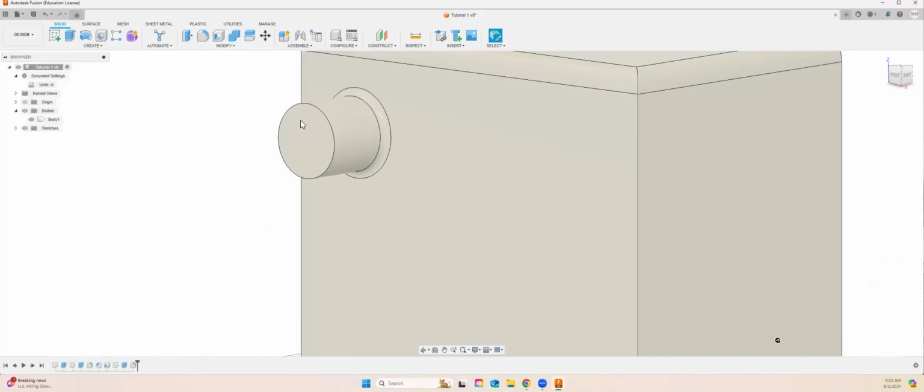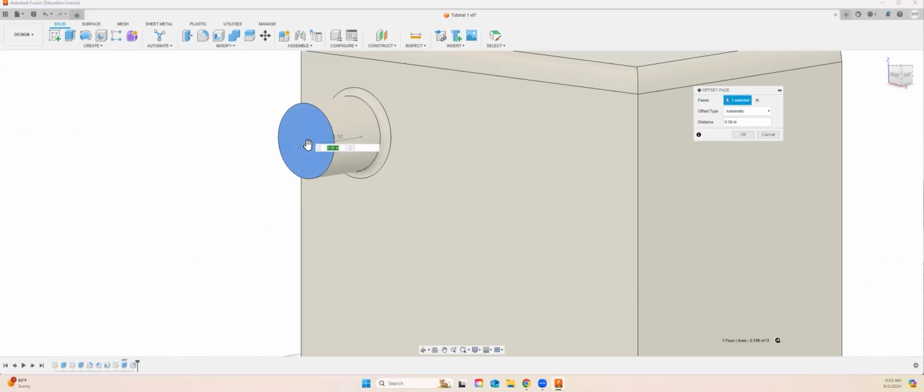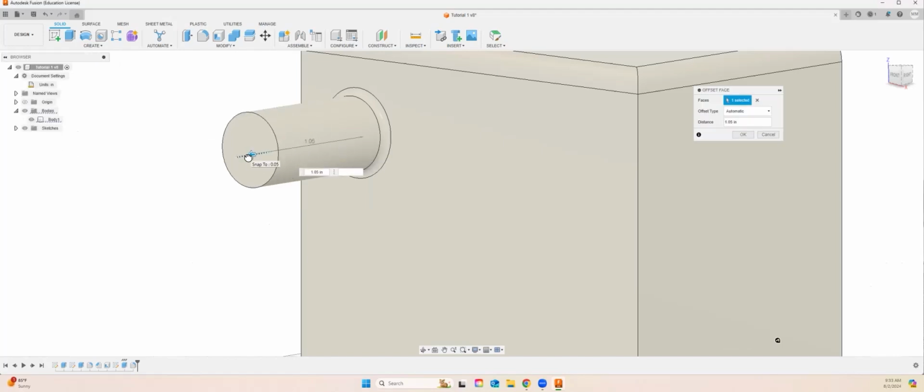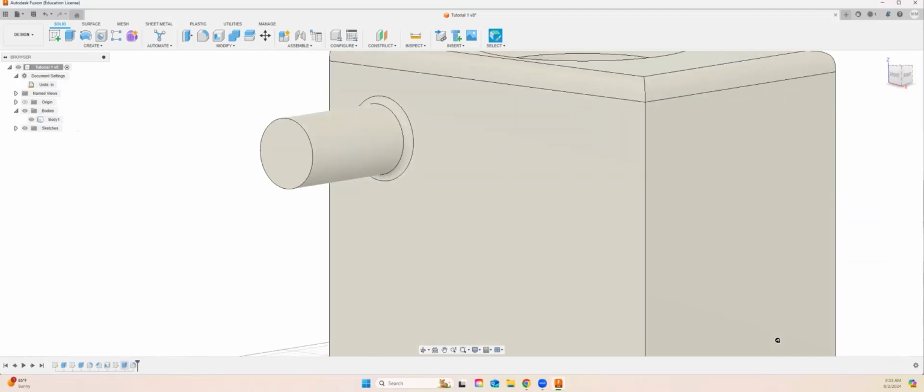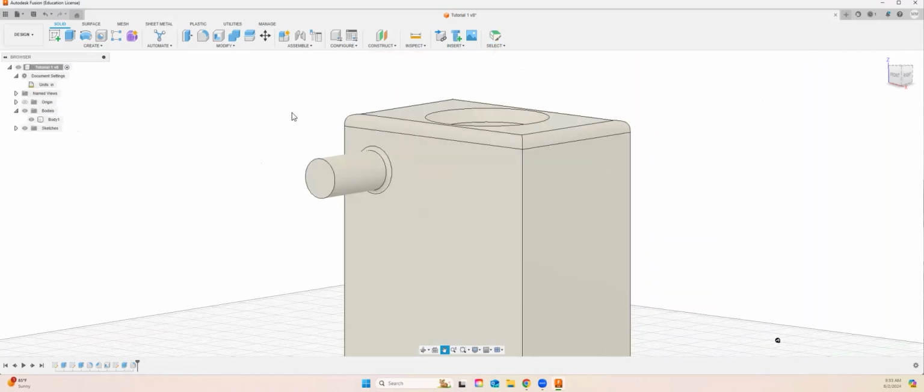So let's say I press Q. I press Q, it automatically changes this. So I want to make this a 1 inch, I guess. You can, of course, just right click over here in the bottom and change the feature if you cannot find it. But different faces, so different commands, different letters will give you that.